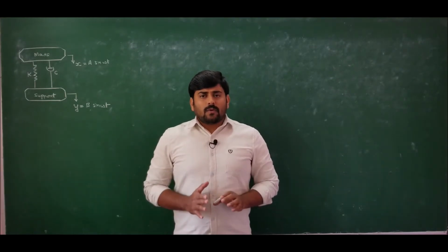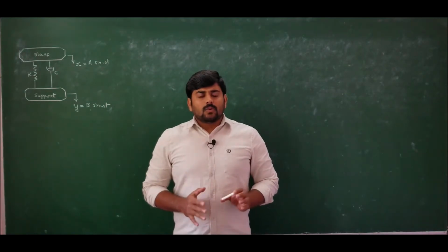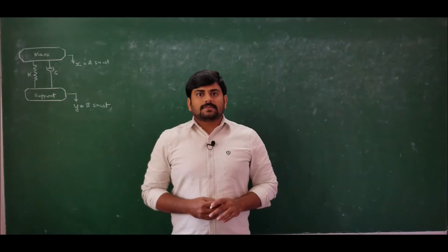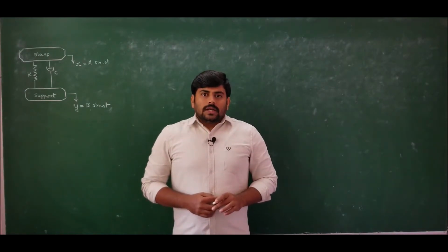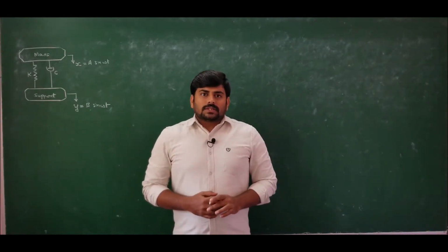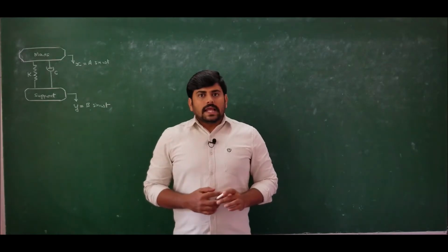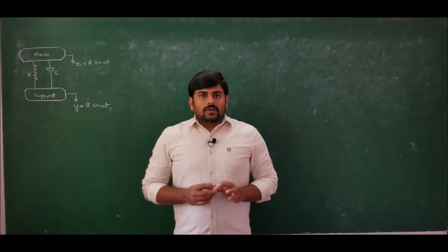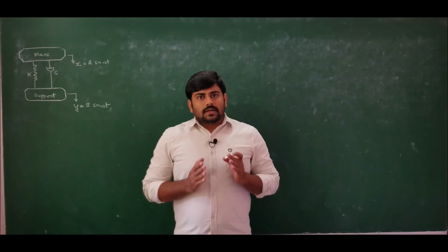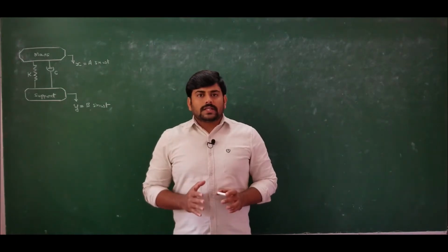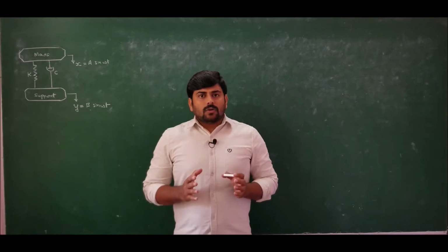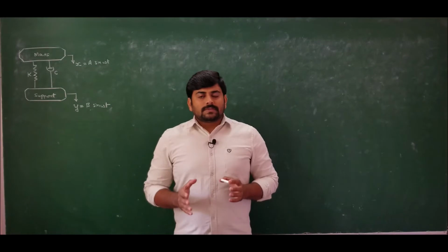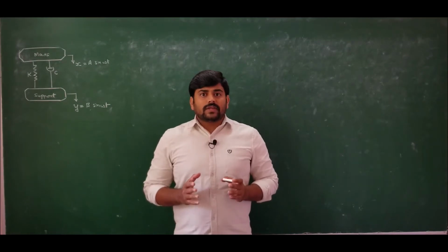Now continuing from the point where we stopped in our previous lecture, in today's lecture I am going to address vibration isolation and transmissibility. Many mechanical machines which we use, like the lathe etc., are all subjected to vibrations. We should not mount the machinery directly to the foundation, because the vibration generated should not be transmitted directly to the foundation, which may lead to sudden breakage or failure of the equipment.